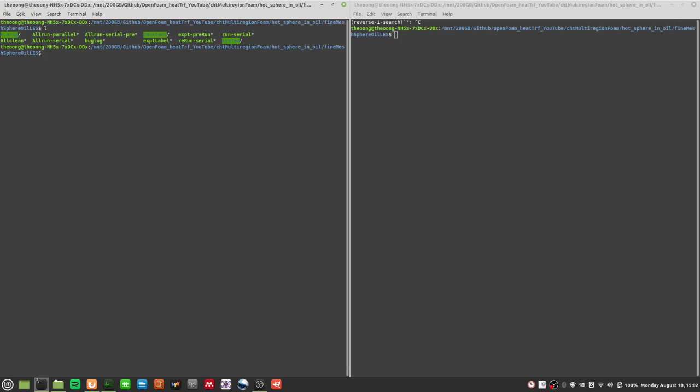Okay, but anyway, without further ado, I'll try to edit this file. So I've actually made a fine mesh sphere oil LES, large eddy simulation. I used snappyHexMesh to mesh it, but in future I might use something like Salome and FreeCAD to do my meshing, especially for more complicated shapes. But for now, I'll just talk about adding turbulence models, which is all pretty simple.